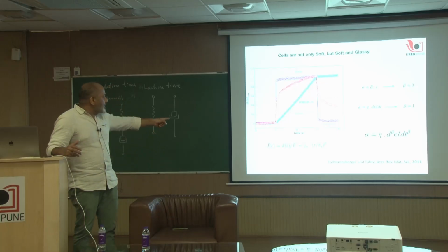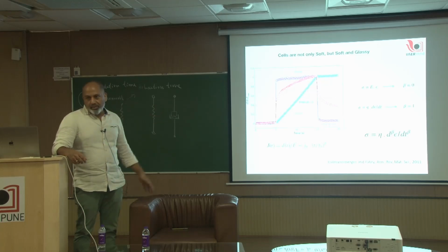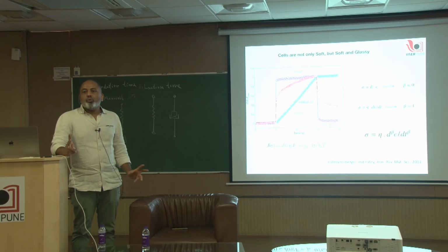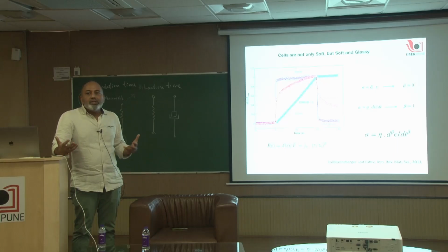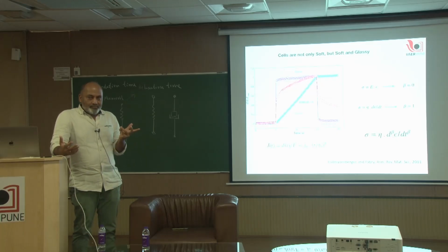And a power law has only, as you see in that equation, just two parameters, J0 and beta. Or tau and beta, not even J0. So just two parameters are required to fully describe the material. Is this the instantaneous compliance or Young's elastic modulus, and the exponent? Now, what is the meaning of this exponent?